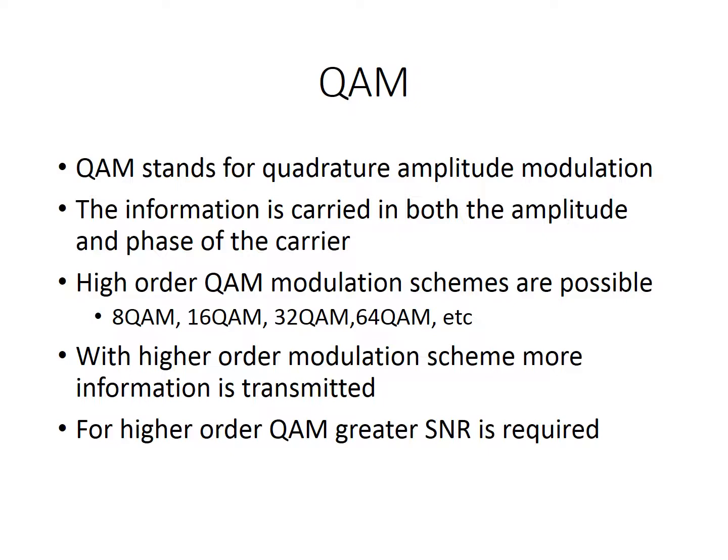In a scenario where the communication channel has high levels of noise, 64 QAM, for example, may not be possible. It would be advantageous for a radio to be able to sense the channel noise levels in order to adapt accordingly and choose an appropriate order of QAM.